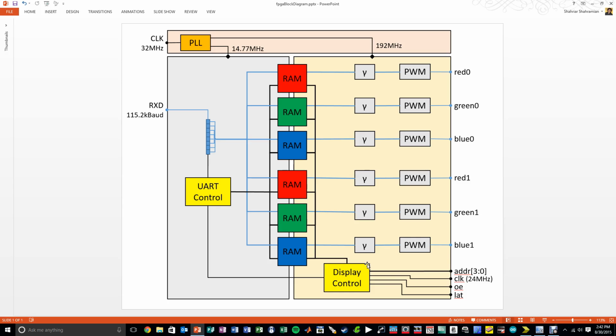So as you know, because an FPGA code, like a VHDL code or a Verilog code, is a description of a hardware configuration, it's very different from sequential code that you write, for example, in C or Java or something along those lines. It's not processed in the same way. It's a description. You're literally describing this as if you were drawing it in hardware, except you're using words in order to do that. That's how a VHDL or Verilog code, that's how an FPGA works.